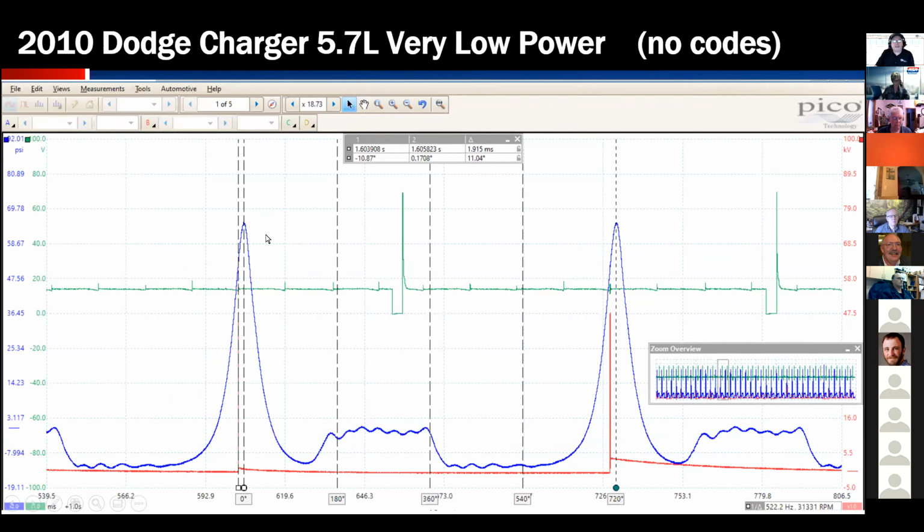Utilizing the same concept we used of looking at in-cylinder pressure waveform, I have added my spark event for the cylinder, and now you guys get to see something extra, as some of my favorite captures go with in-cylinder waveforms. I like to add the injector pulse. And the injector pulse, by the way, is in perfect timing in this engine, happening during the exhaust plateau, beyond the scope of this class. Where I was headed was, where is your spark truly being delivered?